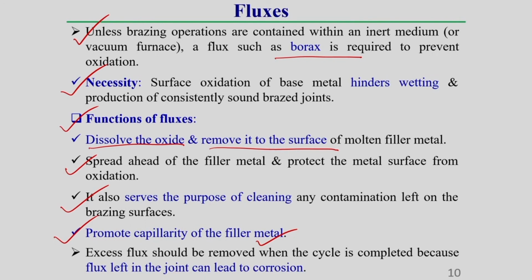But another thing you should keep in mind is that excess flux is not good, because excess flux should be removed when the cycle is completed. Flux left in the joint can lead to corrosion, because flux can have some corrosive property. So, if you use excessive flux, then the residue of that flux can have a corrosive effect.